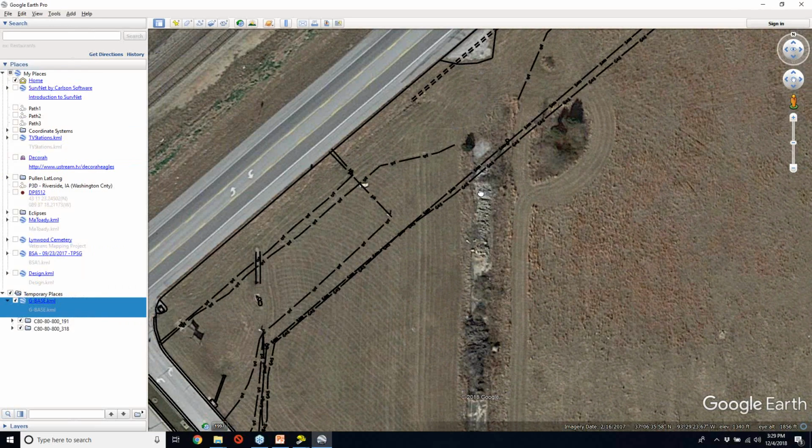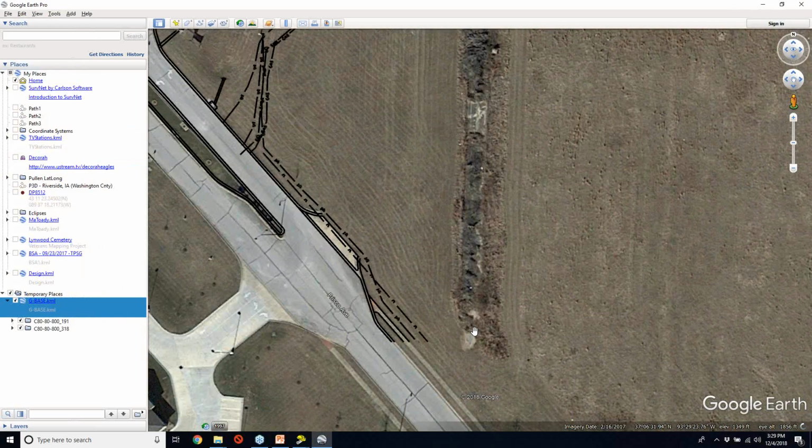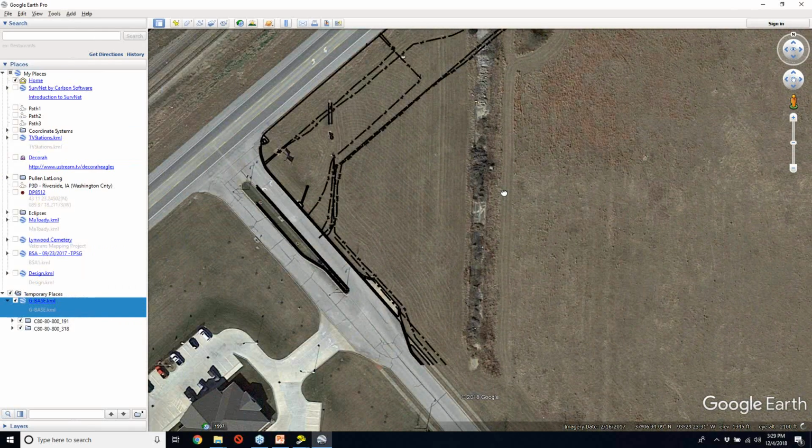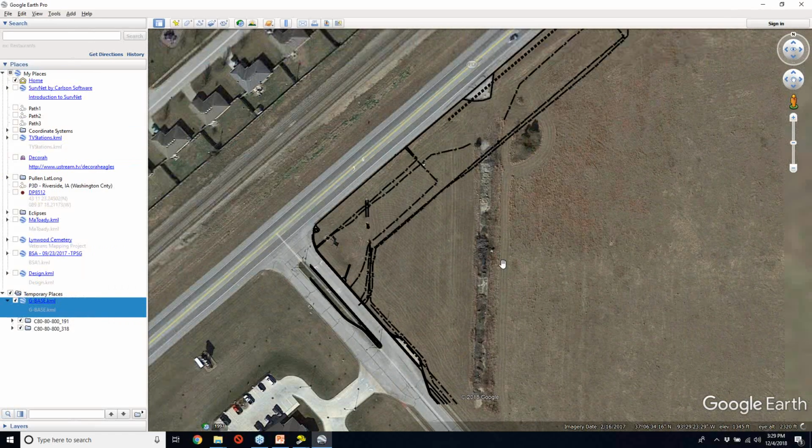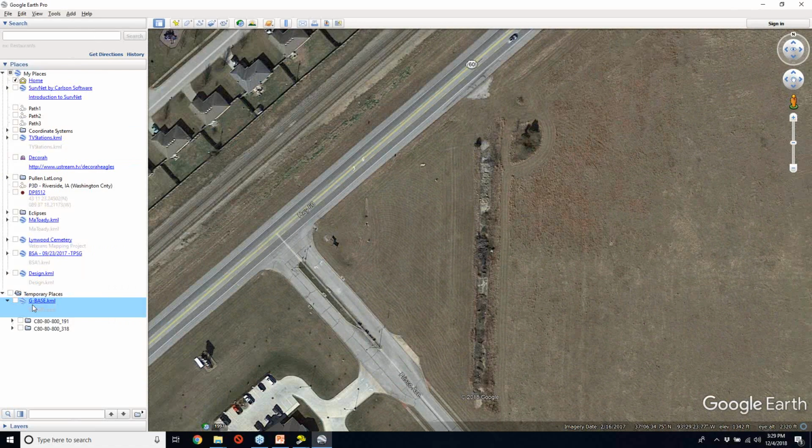What if we were to utilize some mapping tools in Google Earth to aid our cost estimating process inside Carlson Takeoff? So I'm going to turn off that polygon. There's a collection of polylines in here, and I'm going to draw in a freeform polygon inside of Google Earth and use that for work to follow.